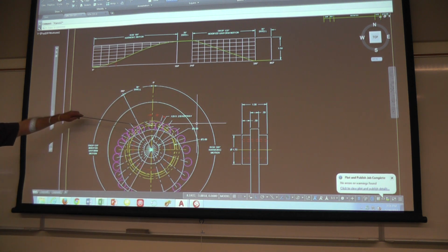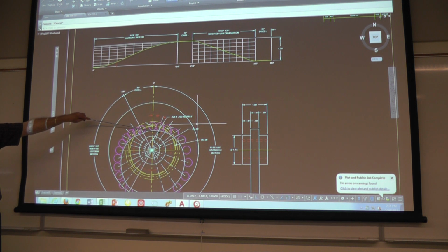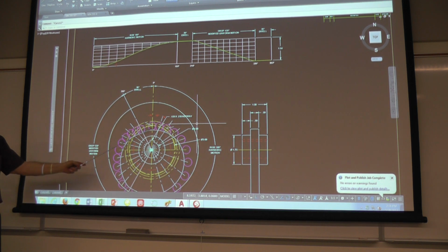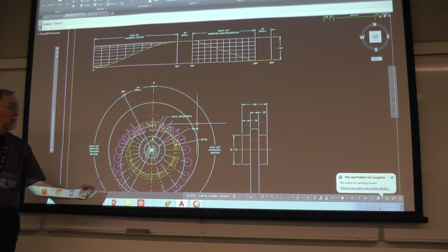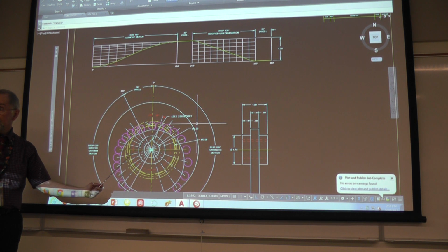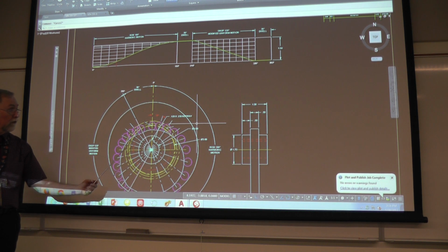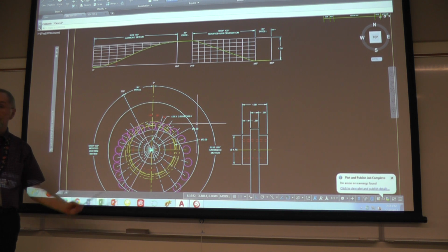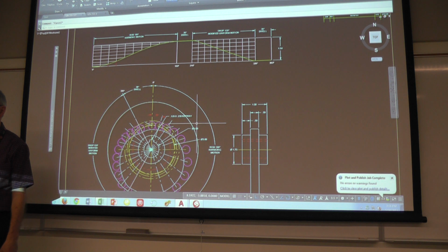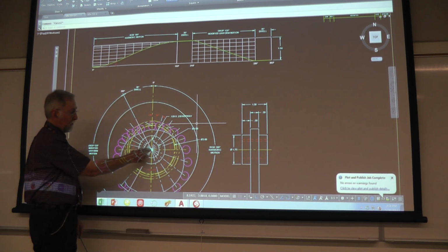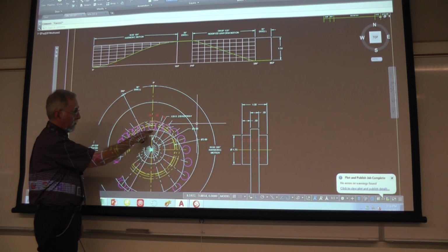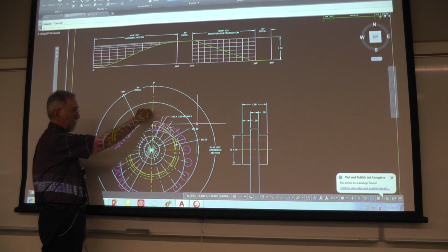All right, the textbook talks about a 3-inch diameter prime circle. The prime circle is the theoretical starting point for the bottom of the 1/2-inch diameter roller. The roller diameter is shown on this drawing as magenta. That's where the roller would start. As I create the plate cam, so here's the center of my shaft, and I want the roller to be at rest in this vertical position here.